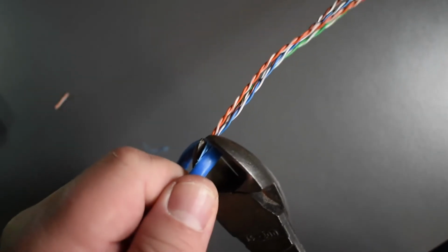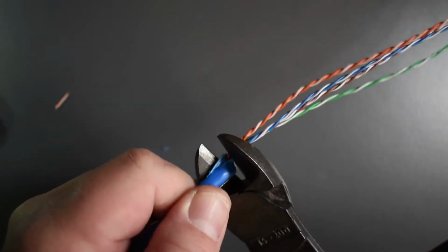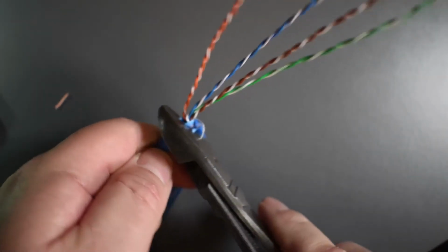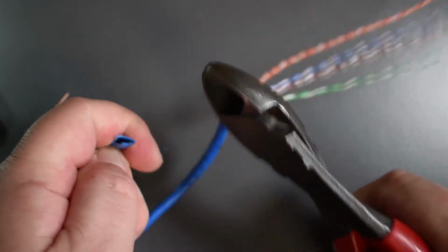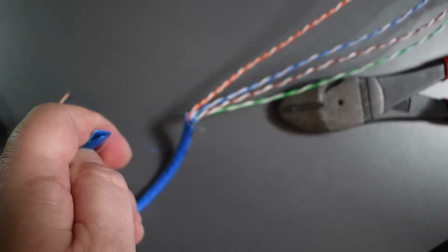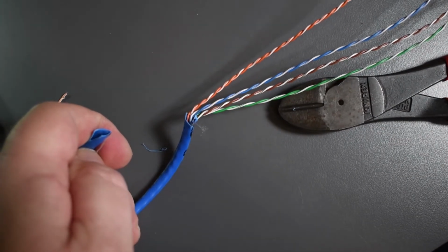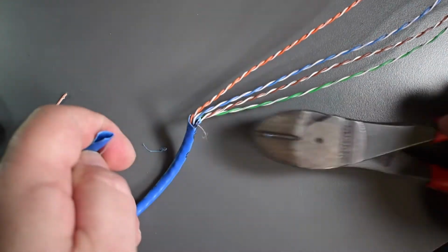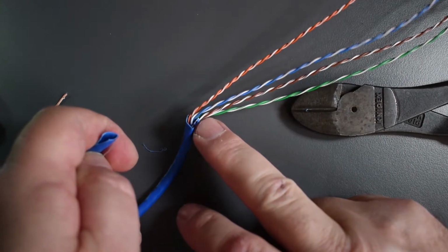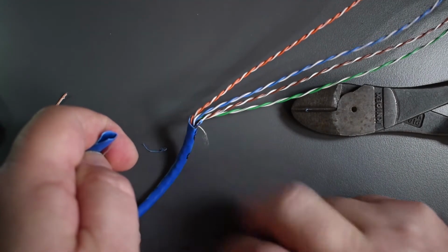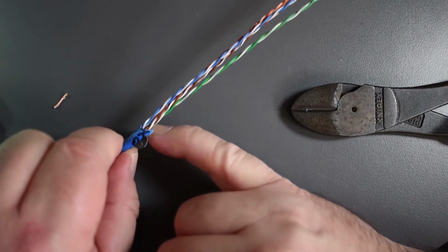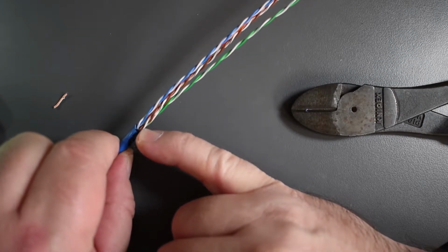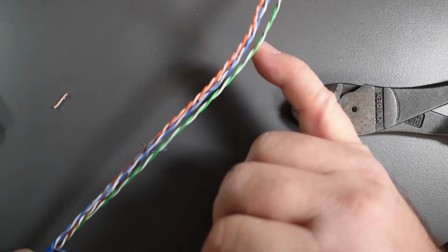I just grab the ripcord and the peeled off insulation, just like that, so I don't damage the wires. Now when you use the side cutters and the ripcord, it's not going to look as neat as if you were using a stripping device, whatever it might be, the clip-on thing, but you're going to have clean, undamaged wires, as opposed to the damaged wires here.